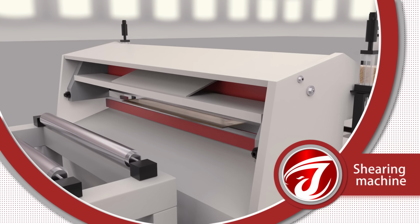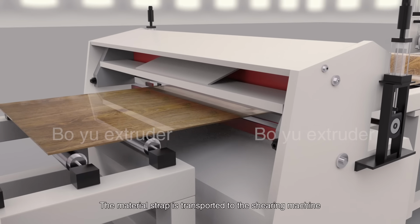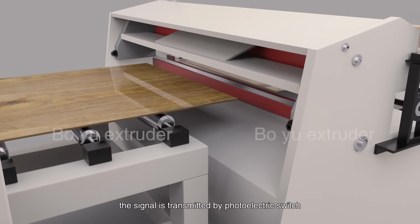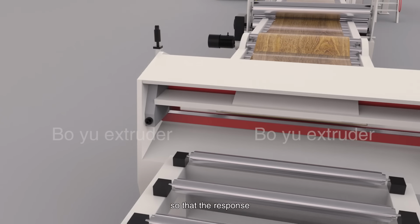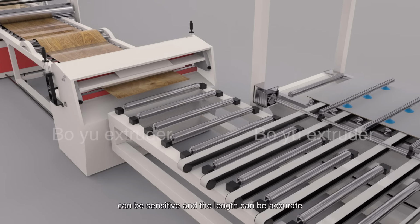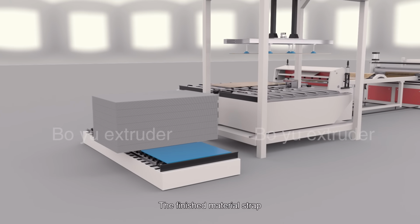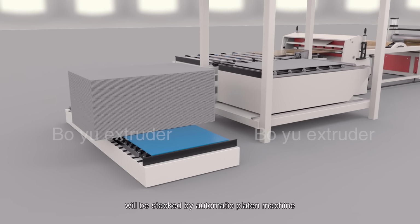Shearing machine. The material strip is transported to the shearing machine by the tractor for cross-cutting. For the cutting length, the signal is transmitted by a photoelectric switch, so that the response is sensitive and the length is accurate. Automatic plating machine. The finished material strips after being cut will be stacked by the automatic plating machine.